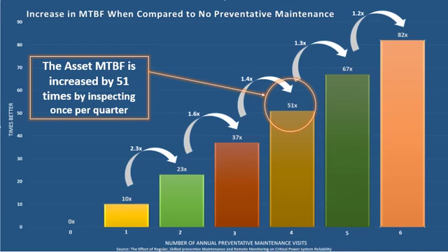So I now have an online monitoring system monitoring the local ambient, irrespective of how many connections are in there. If one of those goes rogue, it's going to increase that ambient. When the ambient increases, I can do the inspection. I'm going to do 4 inspections a year, because using the maintenance inspection window, I have ease of access, and these inspections take literally minutes.